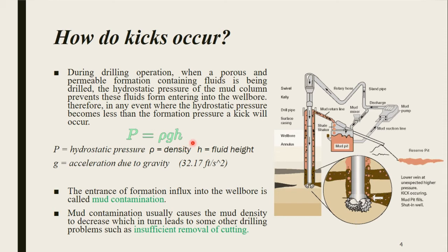In any event where the formation pressure becomes greater than the hydrostatic pressure, the formation fluids will enter the wellbore, and in this case, a kick will occur. And during this kick, the formation fluids will be contaminated with mud. This is called mud contamination.